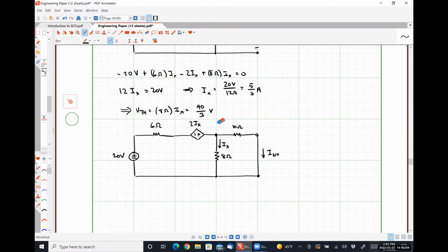We could have done it this way. It would have been a little weird, but that'll be all right. That's the wonderful and sometimes terrifying thing about nodal analysis and mesh analysis. We can really choose our reference to be wherever the heck we want it to be. It's just some things are a little bit easier than others. I would agree that the bottom node here is probably the easiest way to do nodal analysis. Although we will have to write a supernode equation because we didn't choose a node as the reference that was tied to our voltage source.